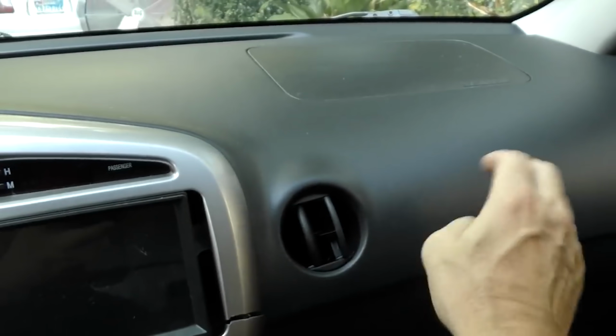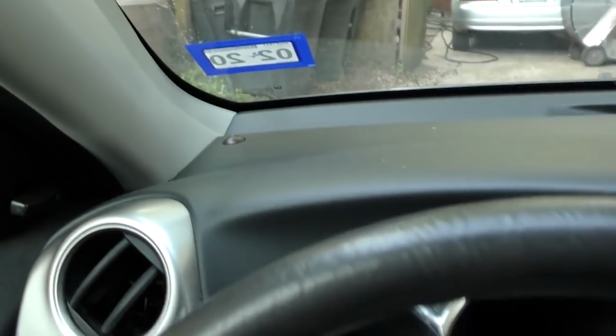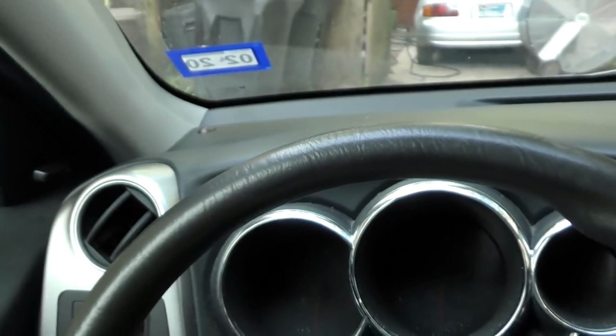Let's say this side's blowing cold and this side's blowing hot. Well, the actuators are up in here. Sometimes just whacking the dash really hard, if it's a stuck actuator, a lot of times they'll unstick. I've had some customers that drove cars for years that way. When it wasn't cold on one side, I'd give it a good whack, and it would start working again. Realize those stupid doors are generally made out of plastic, and they can stick as they age, and if whacking works, what the heck?